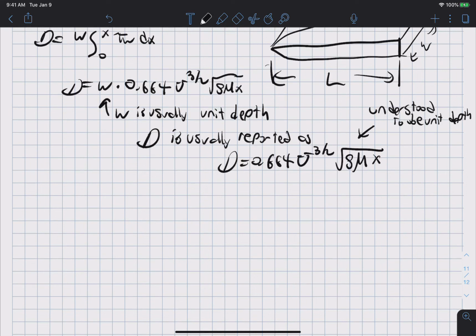And then the drag coefficient for the flat plate, CD is equal to D divided by the dynamic pressure, basically rho u squared, times A, and this is actually the planform area. These flat plates are assumed to be infinitely thin, so a frontal area makes absolutely 0 sense.